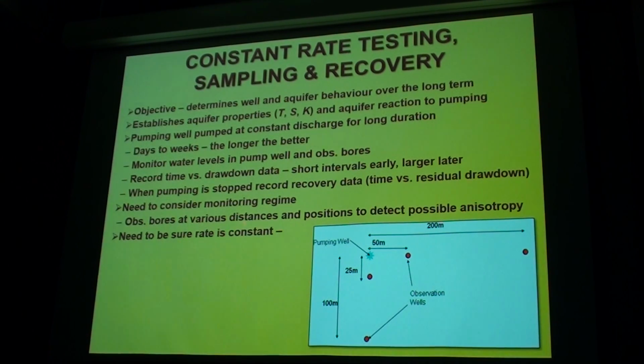You need to be sure that the rate of discharge out of the well is constant, not changing. That'll affect your calculations quite wildly. Okay, constant. Otherwise, things become intensely complicated. You can't really do anything. You can measure that in various ways: flow meter, orifice meter, rectangular notch. We use all sorts. The pumping contractor will have one. They'll have to give you calibration certificates to let you know that it does indeed accurately record the discharge rate.